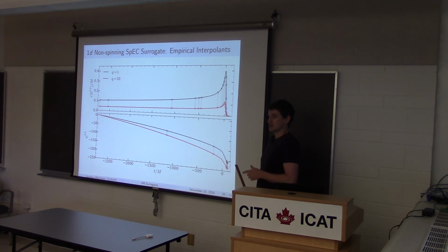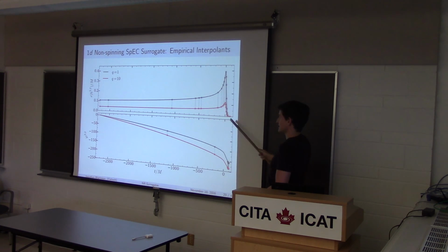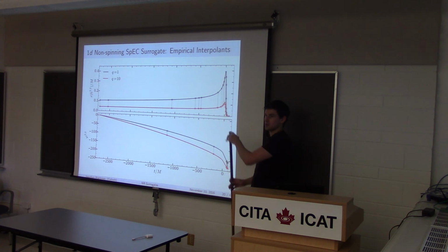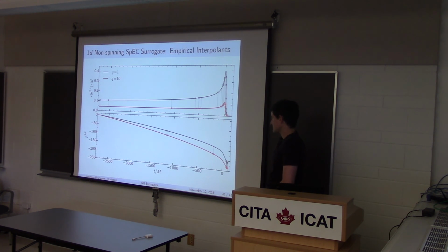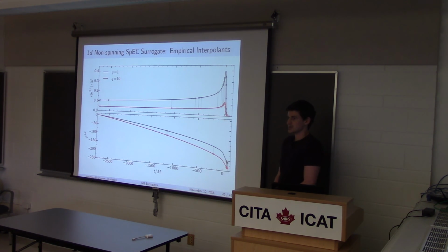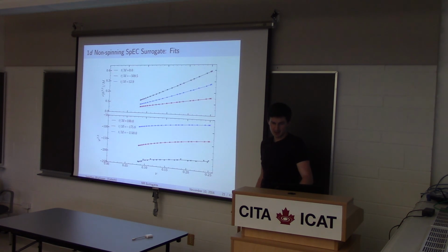We would look at that projection error versus number of basis elements plot, and it would probably look something like this, where it decays exponentially at first and then levels off once you hit noise. We basically would just ignore all those noisy singular values and just use the ones that actually matter. In this case, you would probably get a basis size of 3, is my guess. Maybe you would need a basis size of 4, potentially even 5. But then if you're only choosing 4 or 5 empirical nodes, you're not going to get 20 of them during the ring down. So that would be one way to get around this. And that would speed up the model, so that would help. And we do this in later surrogate models.